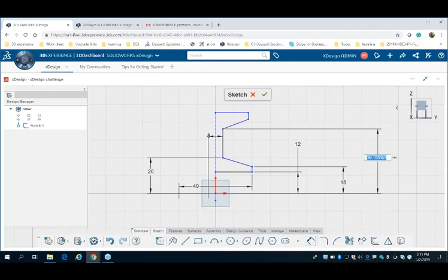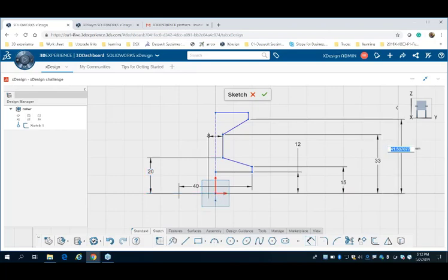Add maximum dimensions to your sketch so that it will be fully defined, and while you are making an assembly, it will help you, because these dimensions will be helpful while you are creating your assemblies, and this will hold your components. Then the last dimensions.